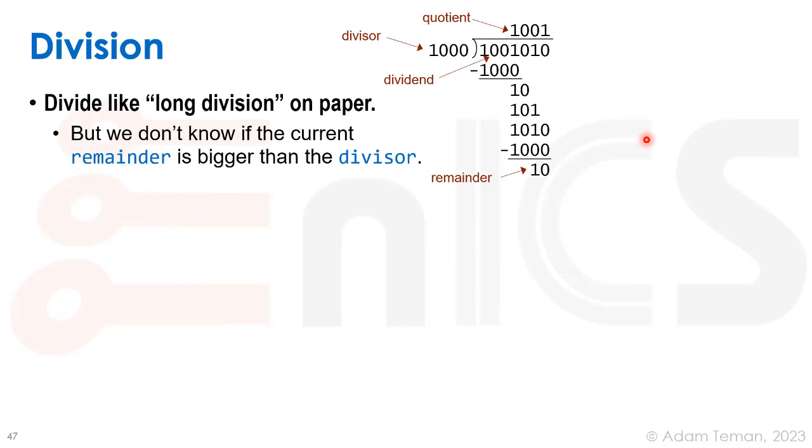Division. So division is a more complicated thing that isn't often talked about that much in different types of computer architecture courses and so forth. That's because it's pretty complicated, and there's not that wide an array of all kinds of optimizations and things that are done with it. It's also not as common, and division is not done as often. And they tell you, for instance, in RTL, never use a divide operation. It's not synthesizable. And the reason is what we're going to talk about now.